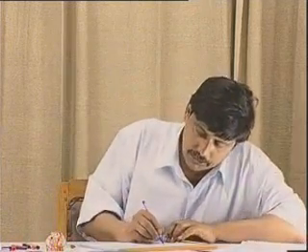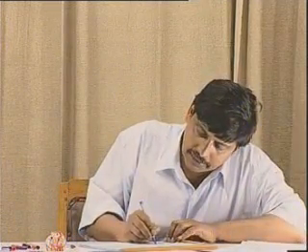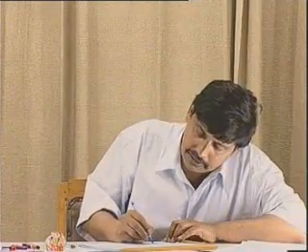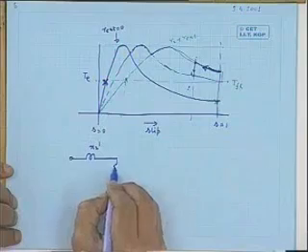Therefore, we find that rotor resistance helps you to improve the starting torque of the machine. And of course, it helps you in another way that we will discuss at great length, but you can easily understand the current drawn during starting will also be reduced. See, what is the equivalent circuit with no external resistance connected in the machine?